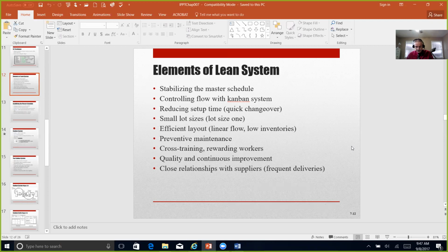So chapter 7, this is kind of where we stopped, where we talk about takt time. Takt time is that German word for the baton that an orchestra director uses to regulate the speed of the music. The lean production system does not allow for any overproduction because you only want to provide what is needed and no more. A stable master schedule is really about how we can levelize the workload, which benefits a lean manufacturing process.